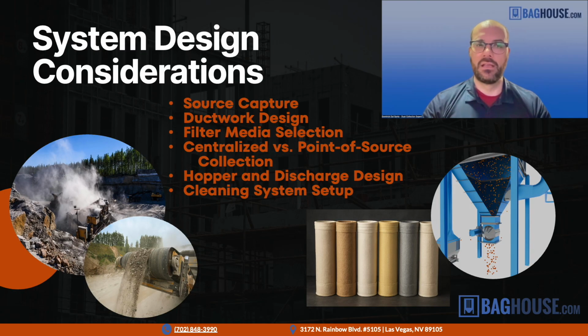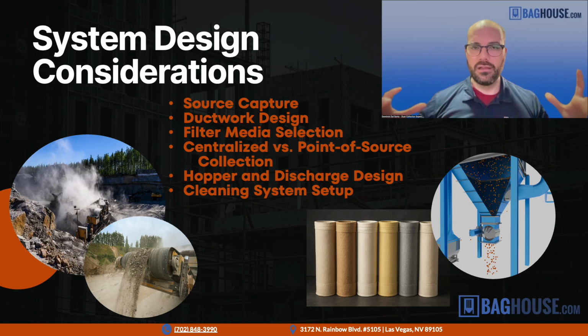Now, if we go to just a few points here about system design considerations, some of the most common things that we get asked that come up with regards to mining and cement applications are these. Source capture. In general, the closer to the source of the dust that you can put the pickup of the dust collection, the better it's going to be. If you try to vent a large area, it quickly becomes impractical. The same dust collector that has 1,000 filter bags that can handle your dryer, if you try to vent a single room, can only handle perhaps a room that's 20 by 20 and only pick up light dust.